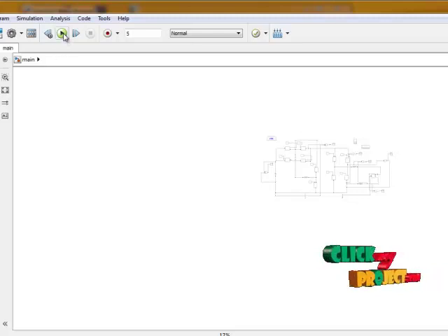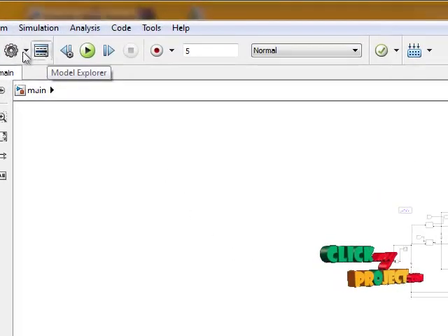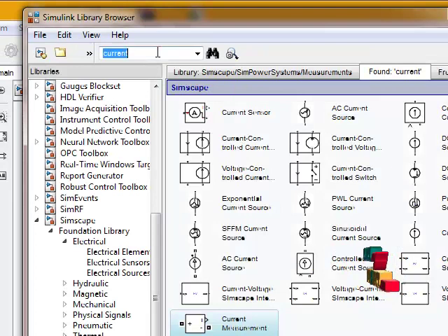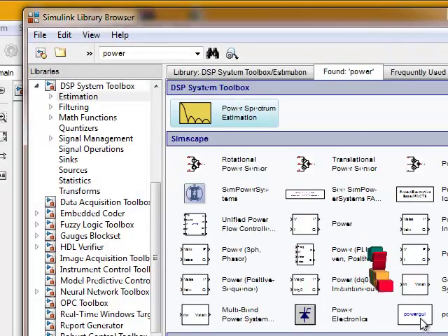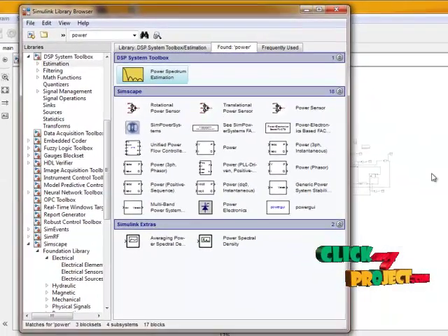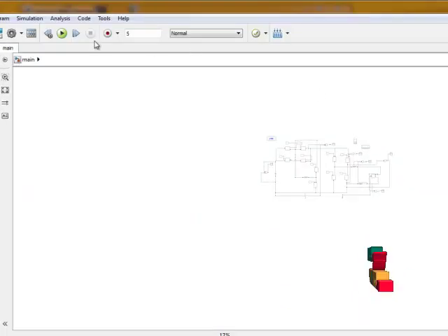So we can complete the designing, and mainly we consider that the powergui is important for the overall power circuit in the Simulink process. Just search for the powergui, and it will give the overall power supply for that. So this is the powergui. We can use the continuous waveform process, connecting the power supplies. After completing this process we can just run it.